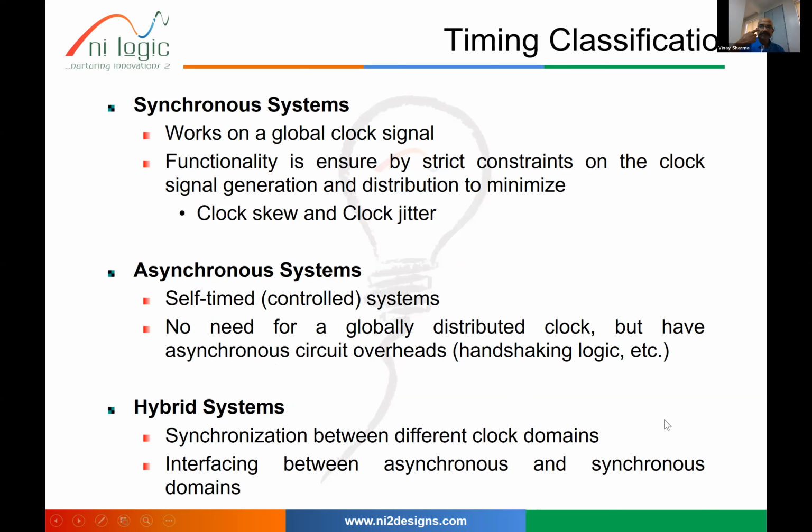Okay. So asynchronous systems are self-timed. That means they work on the handshake. So generally in synchronous, what happens? It's a pipeline logic. Everyone does the work at a given time frame. Let's say the system is operating at 100 megahertz, so the clock period is 10 nanosecond. So every block gets 10 nanosecond of time to complete the job. Okay. So 10 nanosecond, work done, push the data forward. 10 nanosecond, work done, push the data forward.